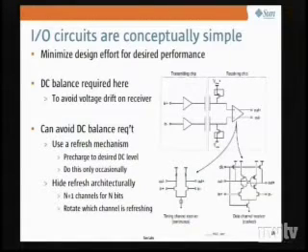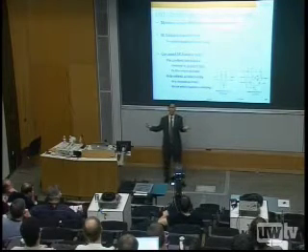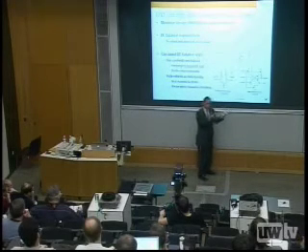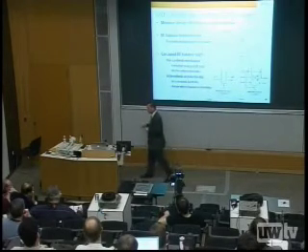The way you clock this is, in fact, for every, say, 64 data bits, I'll have a side channel that's a clock channel that carries clock. And you can't have the clock channel be clocked, because what would clock it? So the clock channel is a continuous time amplifier. All right, so very simple circuits.